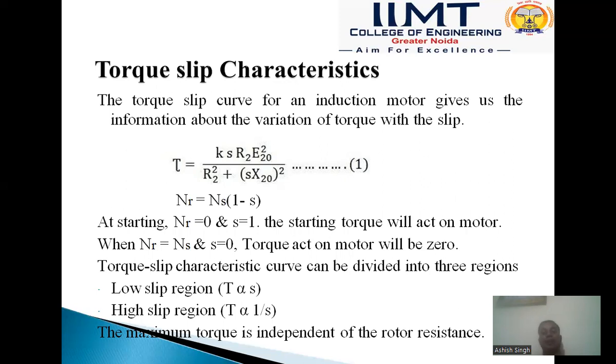So torque at high slip region is inversely proportional to slip. In this high slip region, as slip further increases, the value of torque decreases instead of increasing.